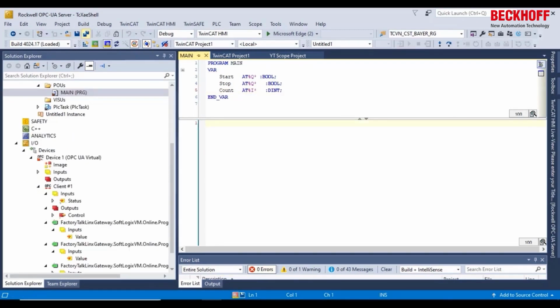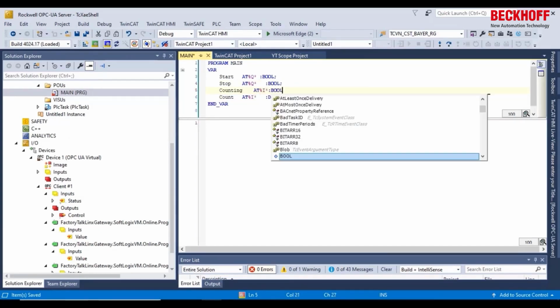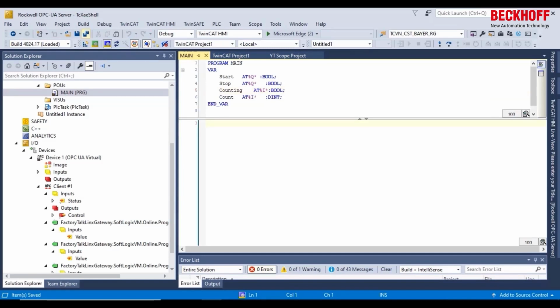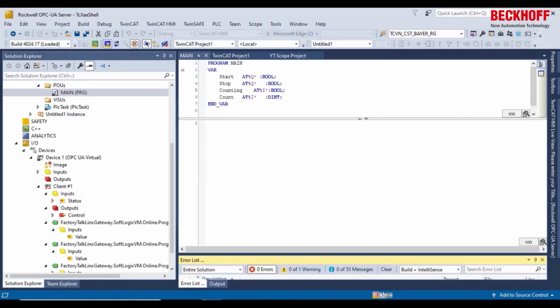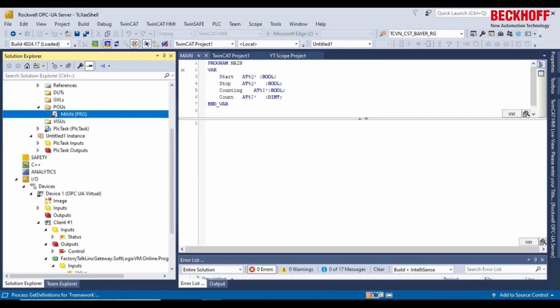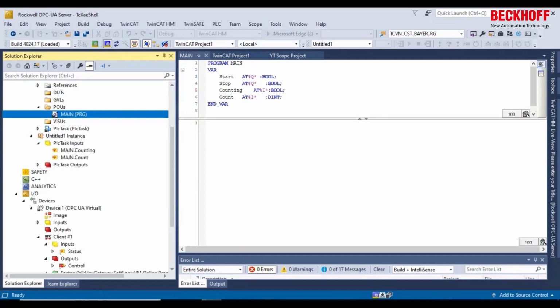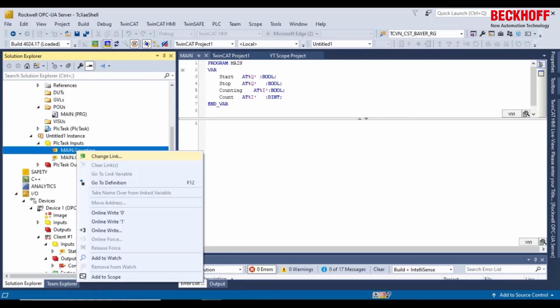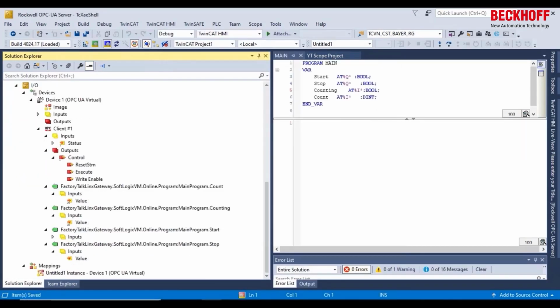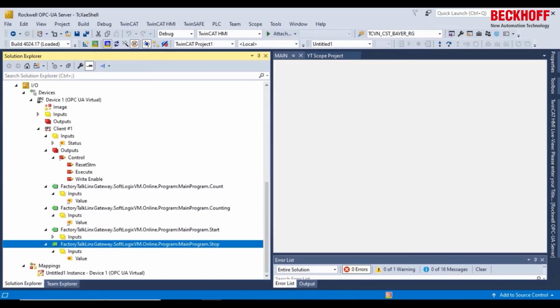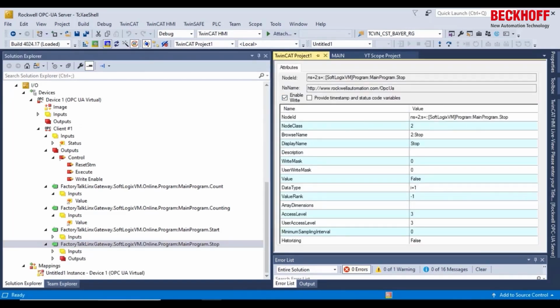And the way we do the linking mechanism, not just do it directly in the PLC in this case, is we could use this virtual device to link some of the OPC data to the PLC, some directly to a MATLAB Simulink object, some to a C++ object. We can link it with different places within the real time. So we compile the PLC, and it gives us these inputs and outputs underneath the instance. And so now I can just right click those, and as I mentioned with the linking, say, okay, that PLC variable, that's going to be this OPC UA tag. Great. So we pick that, and it links, and we can continue down through most of the other variables that we're reading in via OPC.